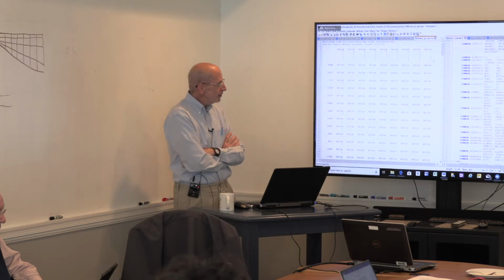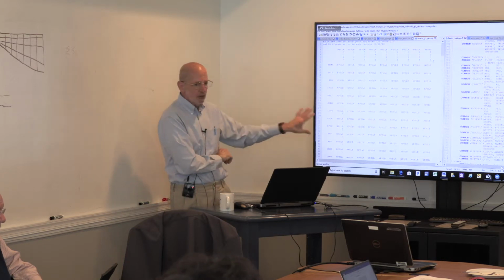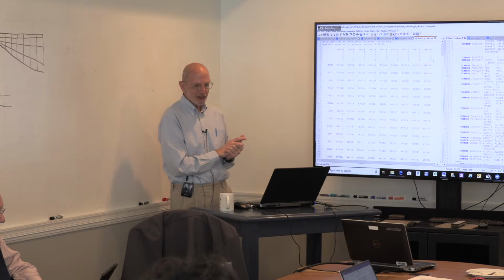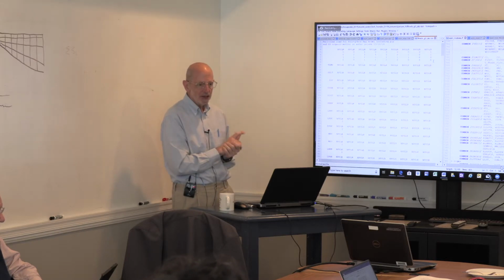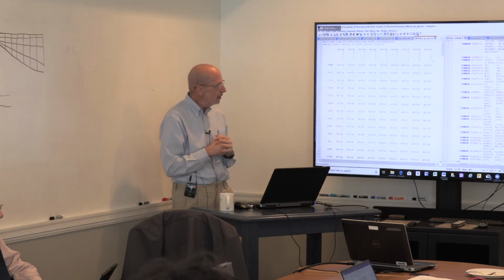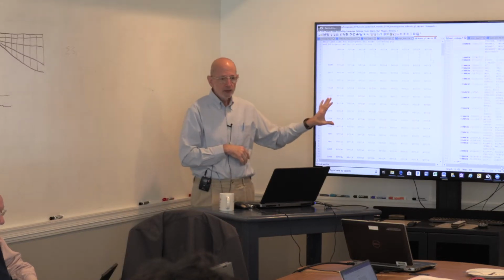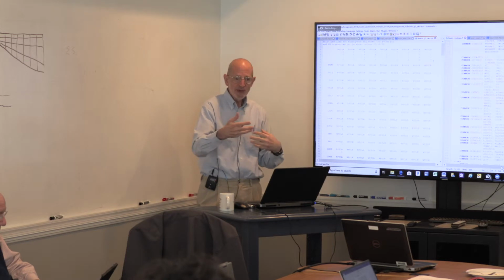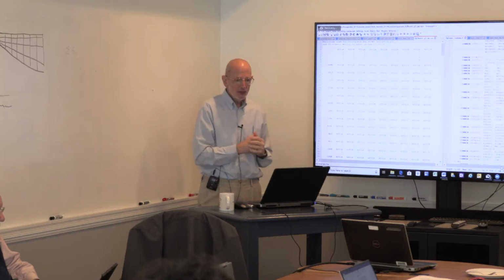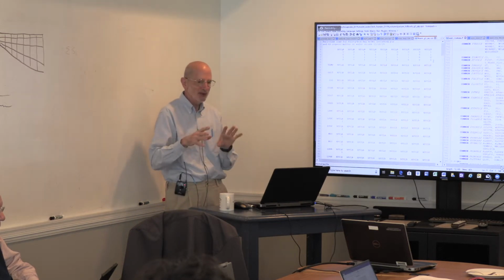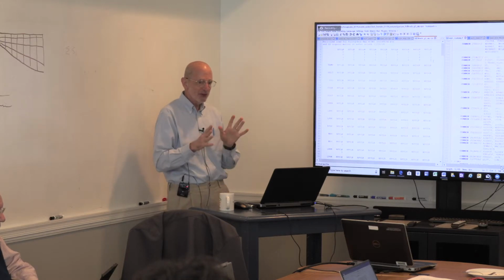Pathogens used to be a variable in this model, and I had a little bit of code in there, so if you got them as most probable number or something like that, it would do it right. Jim has given you an approach. If you don't want to go into the code, Jim has told you how to do it. For temperature, the one time we did a power plant, I actually went into the code a little bit and made it deal with heat. These loads are assumed to be kilograms per day. By the way, I suppose it's in the manual, but it assumes kilogram per day. So if you wanted to have kilograms of temperature, you could work something out, or you could do it right. I'd prefer to do it the right way.